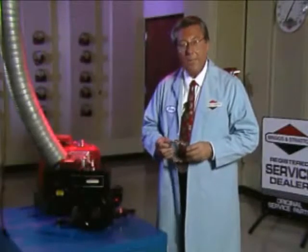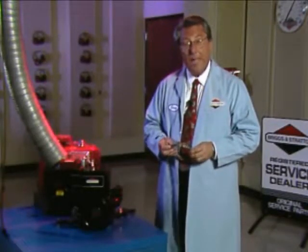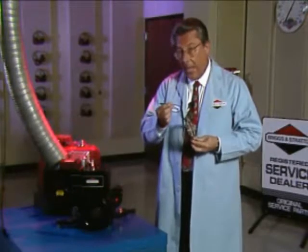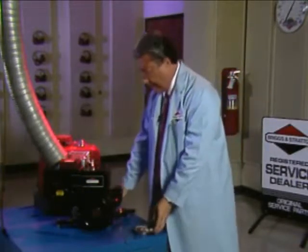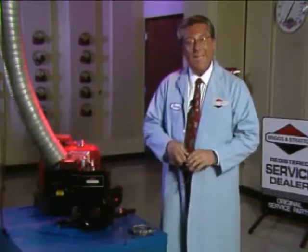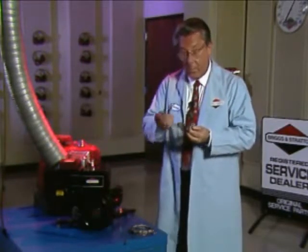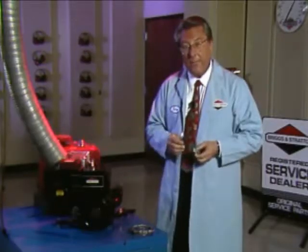The first test is to measure AC volts. An AC voltage test is used when the stator or stator harness does not contain a rectifier. The second test is measuring DC amps. A DC amp test is used when the stator or stator harness contains a rectifier.